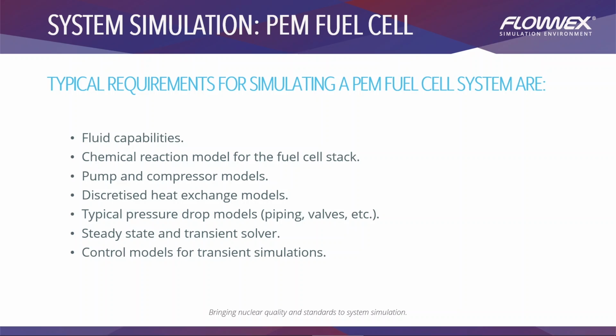So typically the requirements for a system simulation would be fluid capabilities such as complex gas mixtures of humid air, chemical reaction models for the fuel cell stack, pumps and compressor models, discrete sized heat exchange models, typical pressure drop models such as piping, valves, and so on, steady state and transient solving capabilities, and then finally control models for transient simulations such as PID controllers.